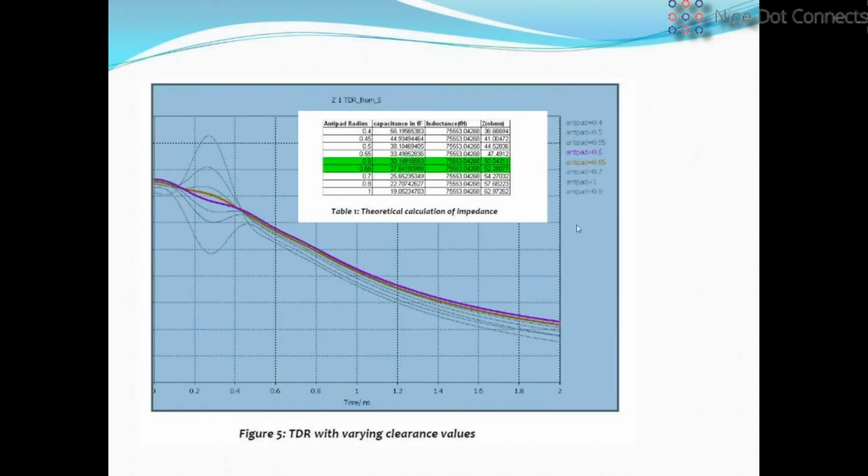So the next slide shows the results of these equations. And you can see here where they found the actual sweet spot for the via anti-pad, in this case 0.6 millimeters. It's performing exactly, and this is not black magic. It's actual rocket science. So I would encourage you guys to be familiar with your via structures, and in future, I would like to get more into this subject.